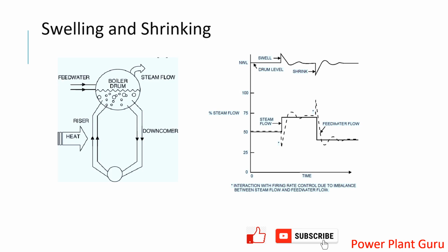So here is a normal case where you have your boiler with a steam drum, a mixture of water plus saturated steam, and then there is natural circulation or forced circulation of water happening like this, and then you have your steam going to the load. If we talk about steady state, what does it mean? Steady state means that your normal operation is happening, then this feed water flow will be equal to your steam flow, and your level is almost constant, not exactly constant, but yeah, the level is the same.